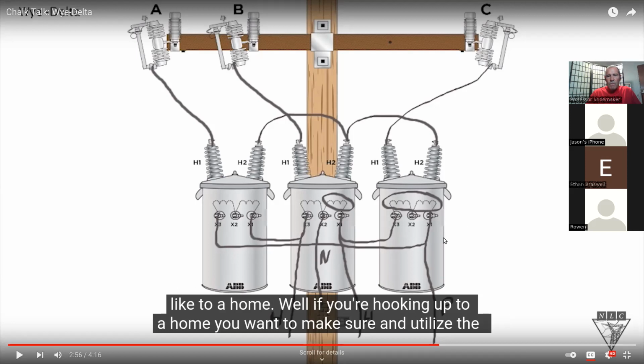It doesn't matter if I carry two wires out of this or one, because they're copper. So one wire out is sufficient. Is everybody up to speed on that part? Yes. All right. Instead of carrying two wires down, one from here and one from here, and make a connection, he just makes a jumper from here to here and then carries one wire down. That's closing the delta is what he's doing right there between all three transformers with that one wire.